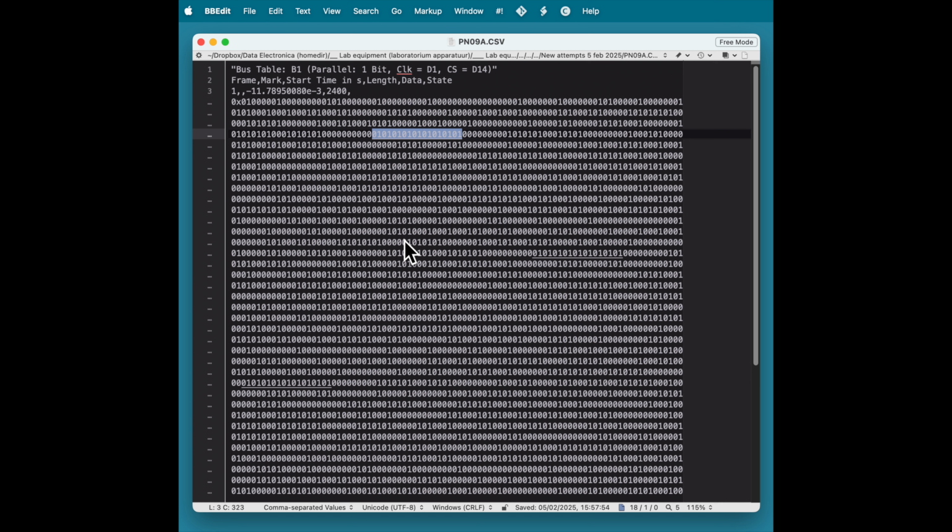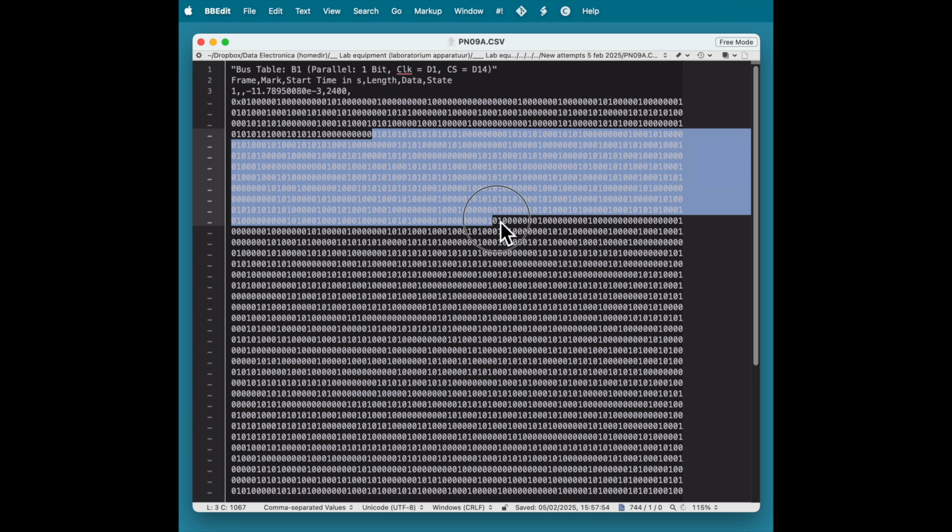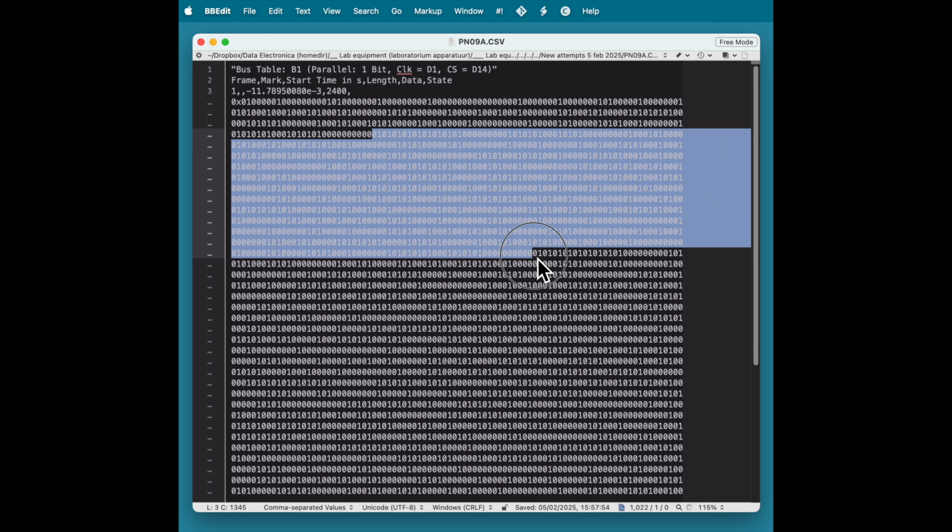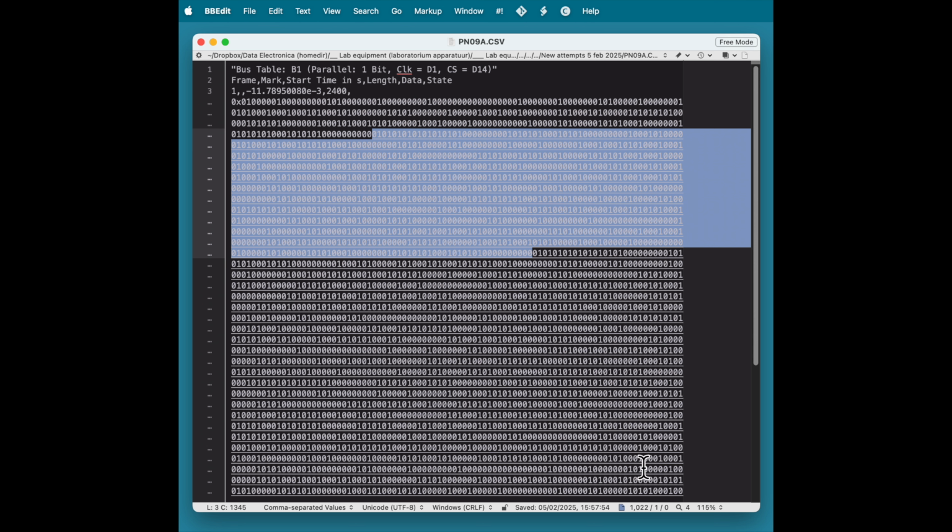So let me try to capture just one of these repeats here. It starts with this 0, and I think it went until here. And that is a repetitive pattern of 1022 we see on the bottom, which is exactly twice 511. So that's fine because we're seeing 2-digit here. I also see that everything is underlined here. That means that the code is perfectly repeating itself. So I was able to capture a well-repeating code from the device. All that is left to do now is take the hexadecimal codes and convert them into binary codes, only the ones and the zeros, and we're ready to inspect the actual sequence.